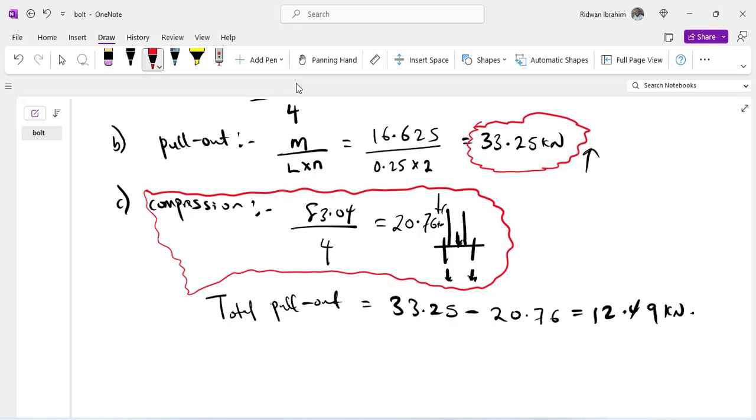So because this force is in your favor, you might decide not to include it in your calculation so that you can have the worst case. So if this 33 kilonewton passes, then it is fine. But if this 33 kilonewton does not pass, then you might try to come and include this in your calculation in order not to have over a large margin for your design.